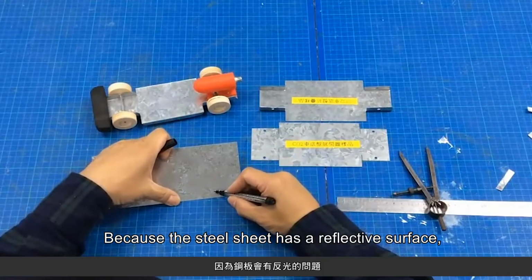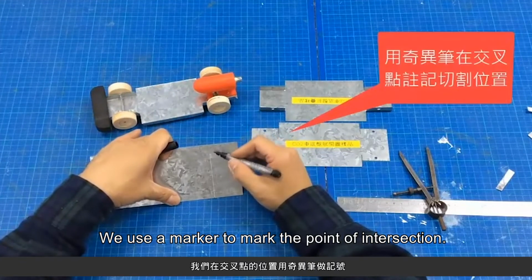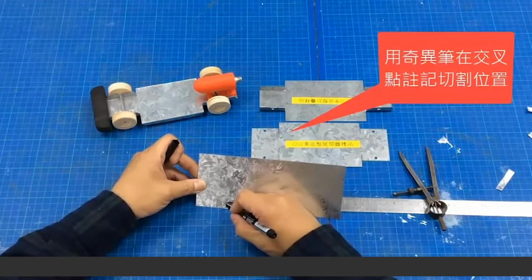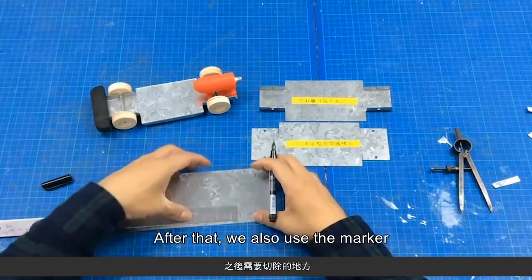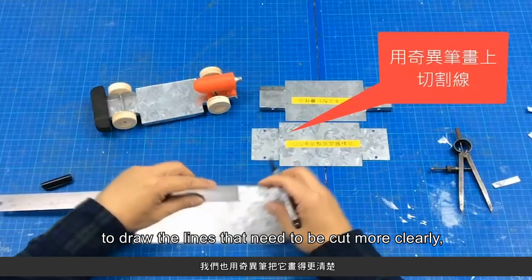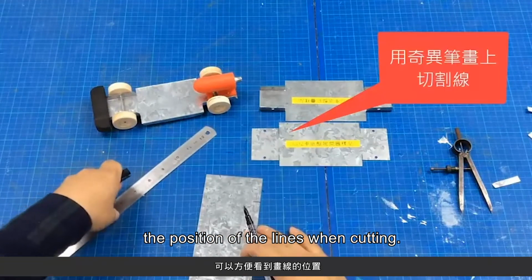Because the steel sheet has a reflective surface, we use a marker to mark the point of intersection. After that, we also use the marker to draw the lines that need to be cut more clearly, so that we can see with ease the position of the lines when cutting.